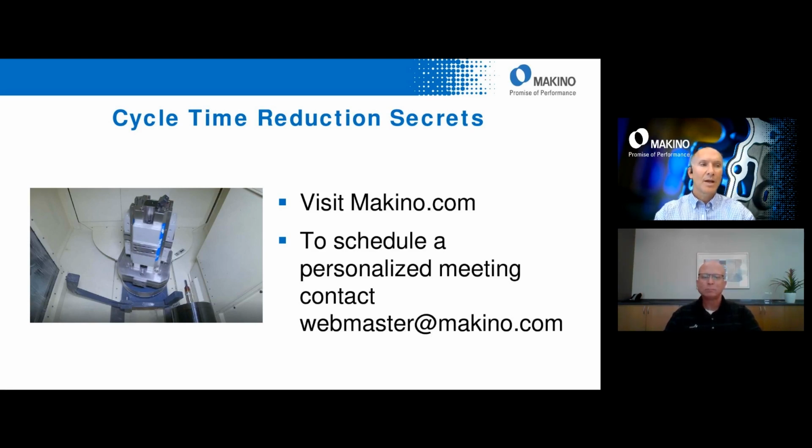Okay. And are there any conditions where M319 should not be used? Oh, that's a good one because I run into that. So M319, as you saw, it opens the shutter door as well. Sometimes people like to put optional stops right before a tool change.